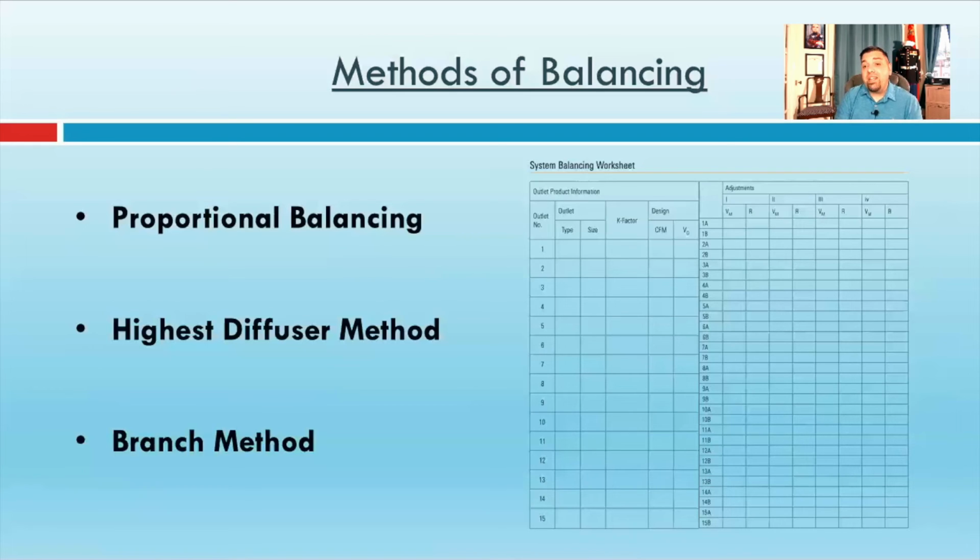They actually are pretty easy, but I'm going to be honest, most residential contractors just don't test and balance their duct systems. And I think a lot of it is because it's not being enforced residentially when you pull a building permit right now, at least here in the Northeast. I would tell you, if you do a commercial space, in order to get occupancy, you're going to have to provide a T&B report. It's the same code, all right? Well, I shouldn't say the same, up to a certain square footage for commercial, but it's only a matter of time. You're going to start requiring testing and balancing, especially in new residential systems or new construction.